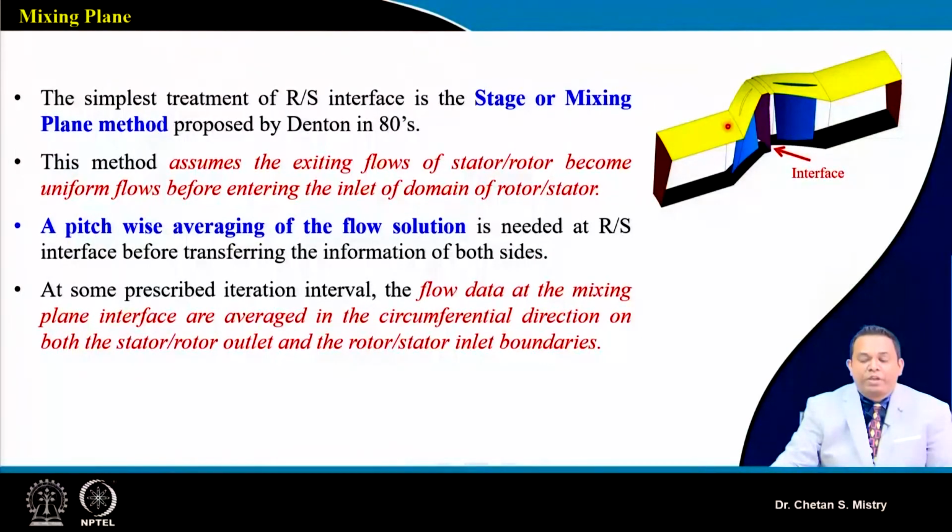So what it will be doing is, when the flow reaches this interface, it will become uniform, and that uniform flow will enter the downstream rotor or stator domain. What it is doing is pitchwise averaging of the flow solution that is transferred from one domain to the other domain.